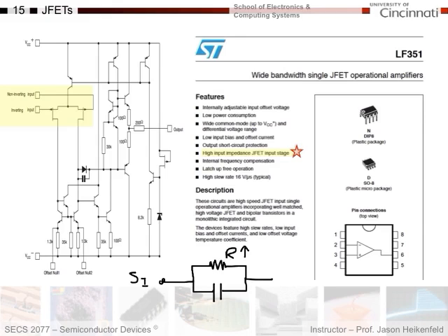And so that means that my capacitance is also going to be low, right? If you reverse bias a diode, the depletion region increases. Well, that's perfect because if I look at impedance, okay, let me erase this here. I always have trouble getting this to erase once I did it. Sorry, that's supposed to be a plus. Plus 1 over j omega C, right?